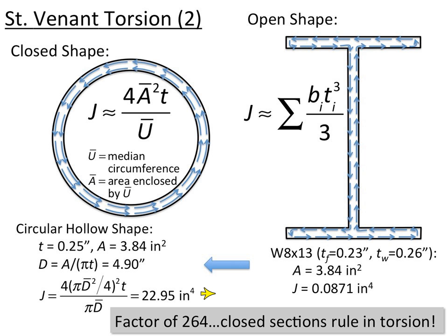So the bottom line here is closed sections rule in torsion. So anytime you have a torsion problem, think closed section, because you're going to get a lot of bang for your buck by enclosing area.